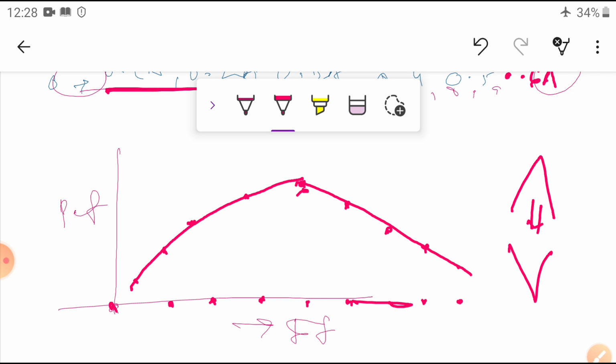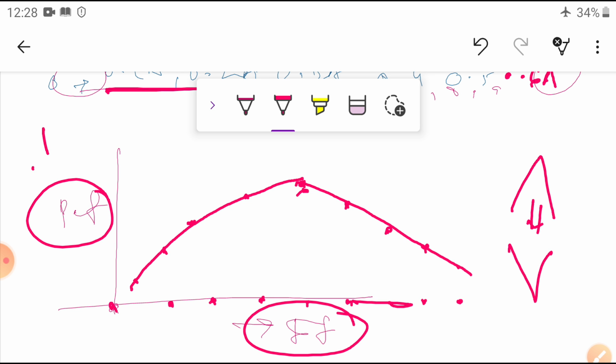Okay, so that means if the field excitation changes, the power factor as well as the armature current also change their nature. That's why we draw the performance of the synchronous motor in the form of V curves and inverted V curves.